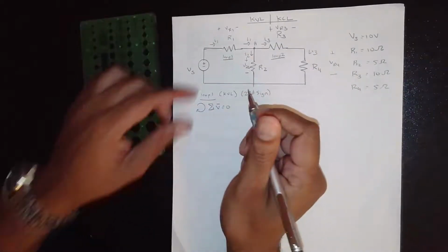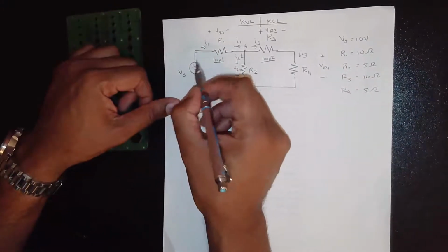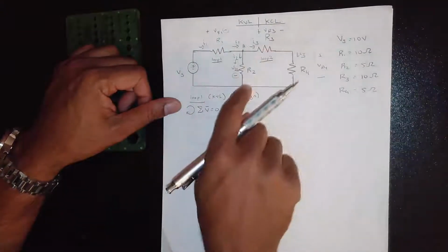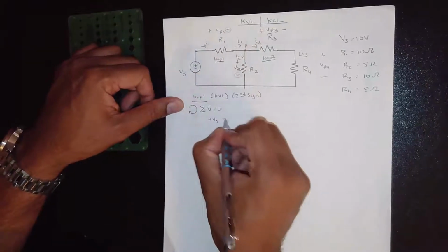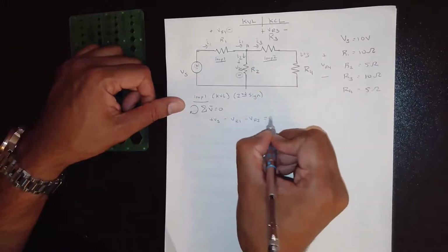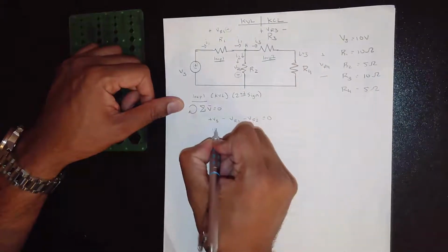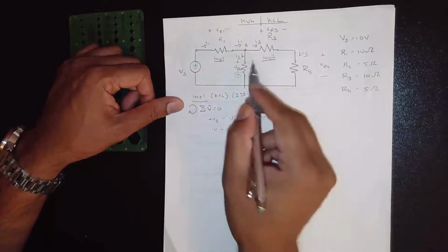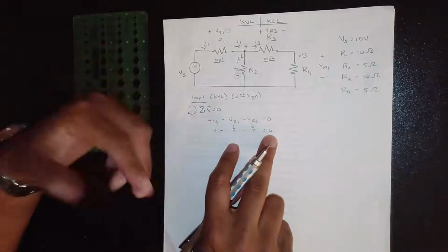So we'll adopt the second sign convention as you travel around. Second sign, second sign, second sign, just like that. You travel around the loop. Then we write down plus Vs minus VR1 minus VR2 is equal to 0. So Vs is what? 10. Minus VR1, I don't know. VR2, I do not know. Equals 0. When I don't know it, it becomes an IR.